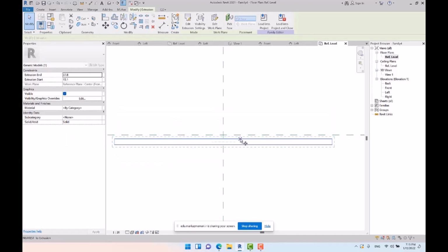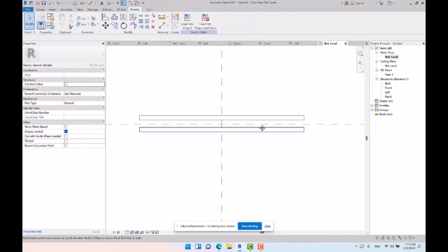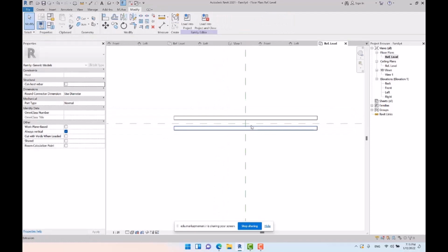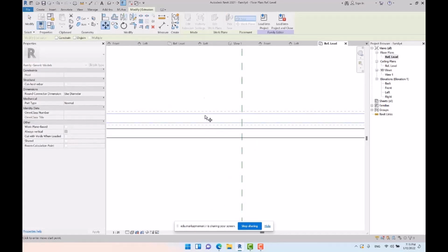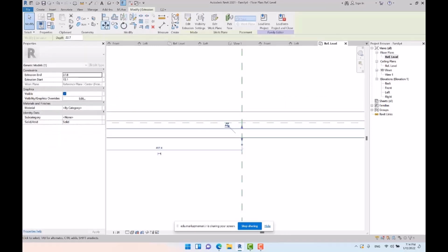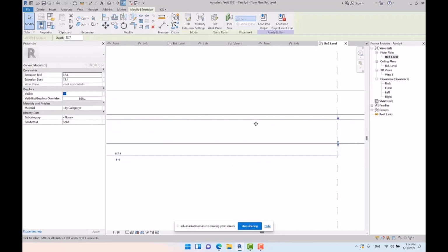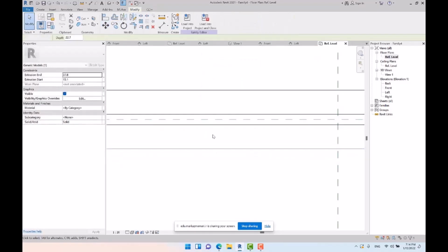Here I can even model it in two layers. So I make a copy, I remove the constraint and I place it here. Well done. First of all, I should move the second extrusion down. I place it right here and then I add one more 5mm offset. Very well. And then I want to move the bottom profile, glass, upwards. I check this join and then I define a 5mm offset.